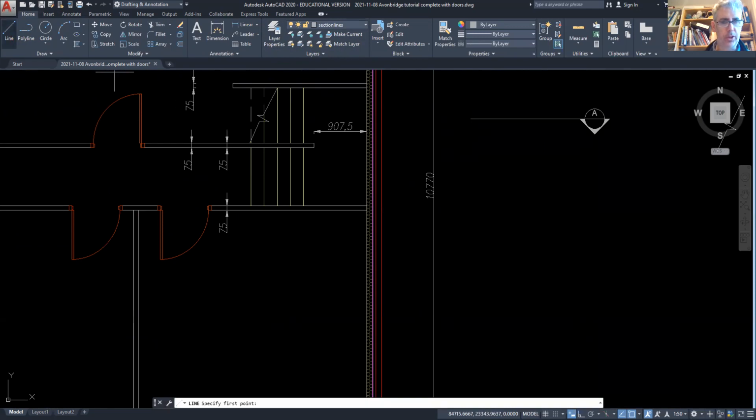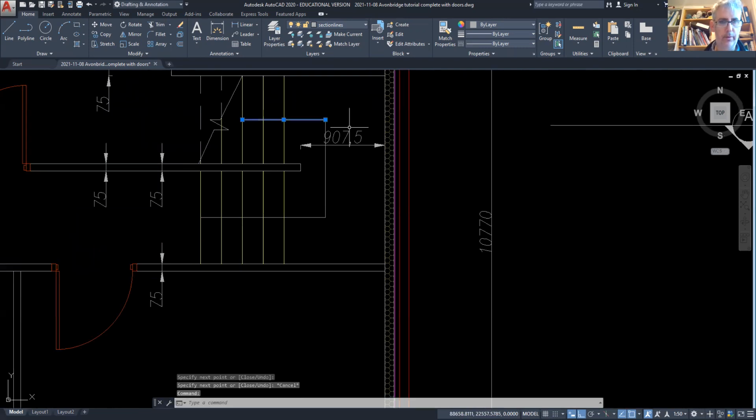I'm just going to use the section lines layer, and I'm just going to make a very simple U-shaped line here. Knock my ortho on, and then bring my line up to there. Try and make it spaced apart from here to here, that distance the same as from here to here. Now we're going to go into polyline,